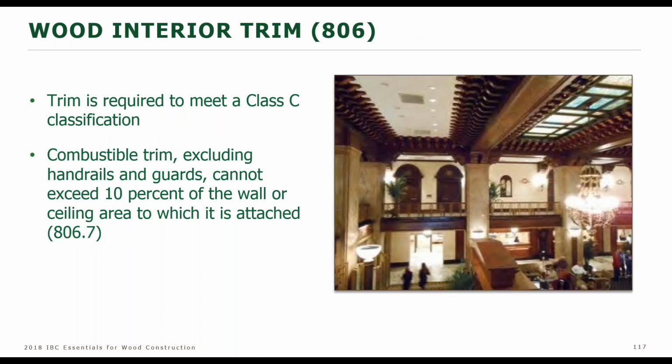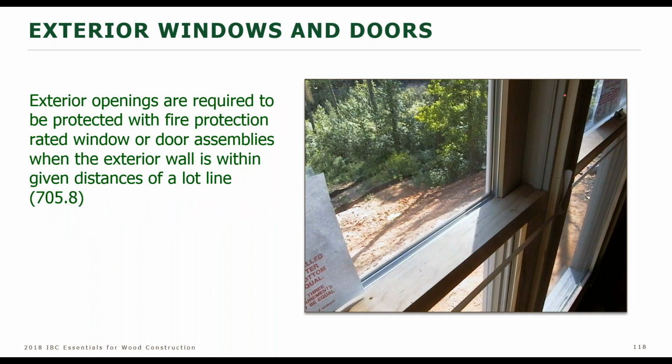Wood trim, very popular. If it is classified as trim rather than being subject to all the requirements for interior finish, it is subject to some of them, simply limited in allowable area of the wall or the ceiling, 10%. And what about windows and doors?